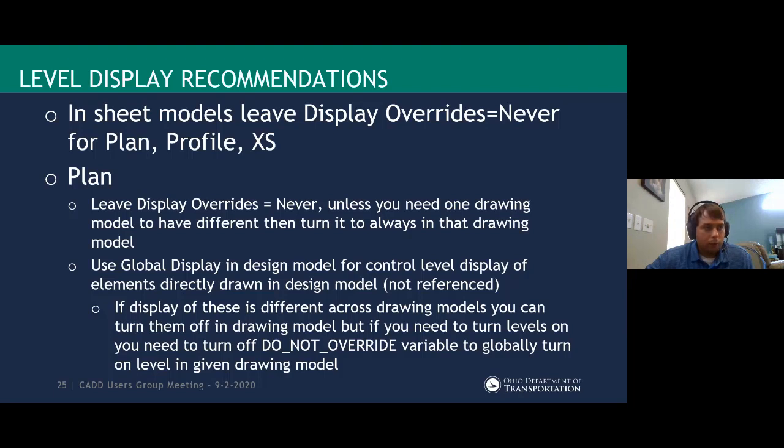So now when it comes to the direct references for plan view, use global display on the direct references in your design model. And then that'll, as you saw from the video, that global display will control that level display. If you need those to be different, the direct references to be different, your only choice is to turn off that variable by going into that given work set config file and setting it equal to nothing.